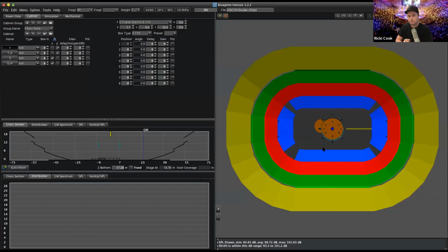So there would be that. Again, reiterating what Croft said, I quite often will grab a 58 or whatever the vocal mic is, and I'll walk back to the console and make sure I've got it dialed in with my voice through that microphone. I've learned over the years that always yields a better result. You can go and set up smart, and you can go and run pink noise through the PA and look at an FFT or an RTA and tune until your heart's content. That might yield you a great result. You might actually be able to pull it off, but at the end of the day, just grab a 58,